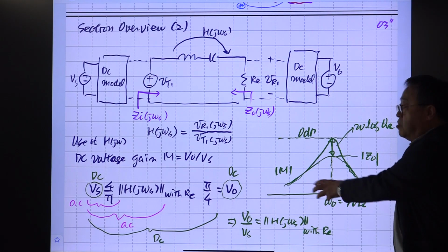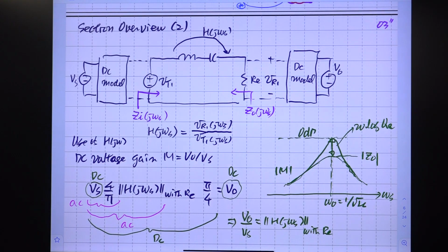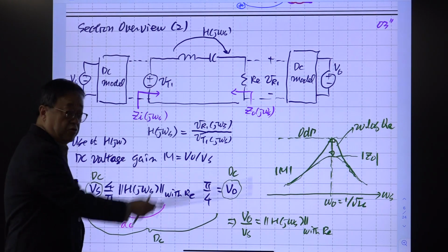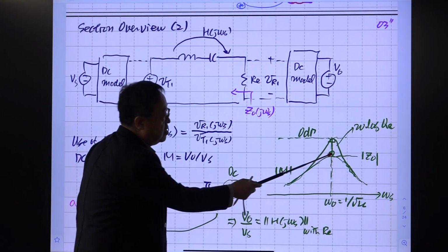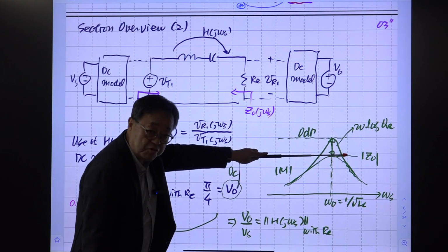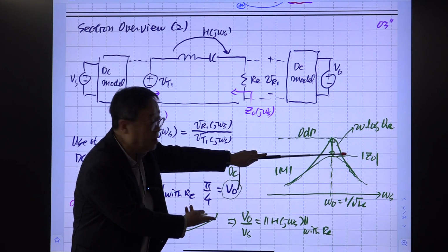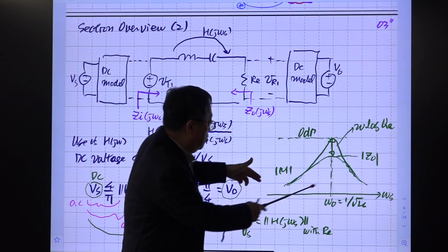Okay? So there is the result used by all the people all the time for the analysis of this resonant converter circuit. This is the exact one. So if you evaluate the transfer function from here to there using simple AC analysis, it looks like this. Okay? It shows something like this because this is a simple second order system. This is a peak value, and this peak value is the characteristic impedance of the tank circuit. You know this. You learned this. Okay? Then with Q, there is a peak. Right? So magnitude is this.